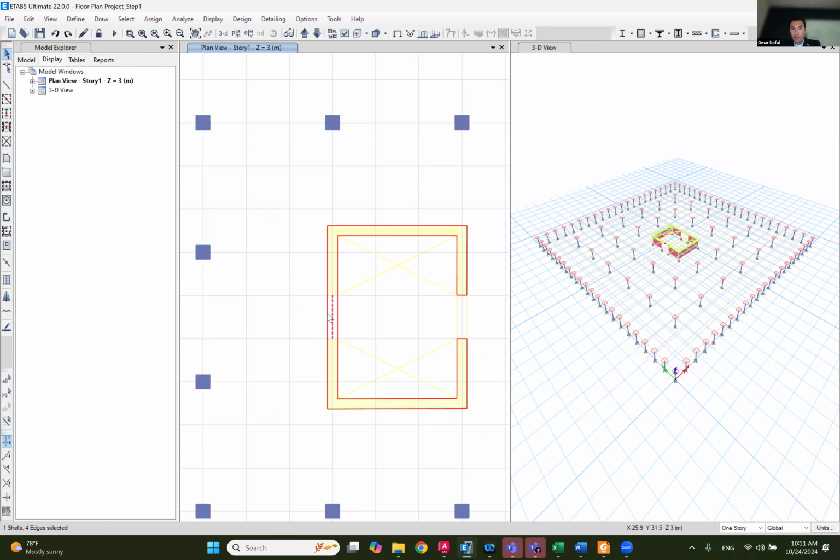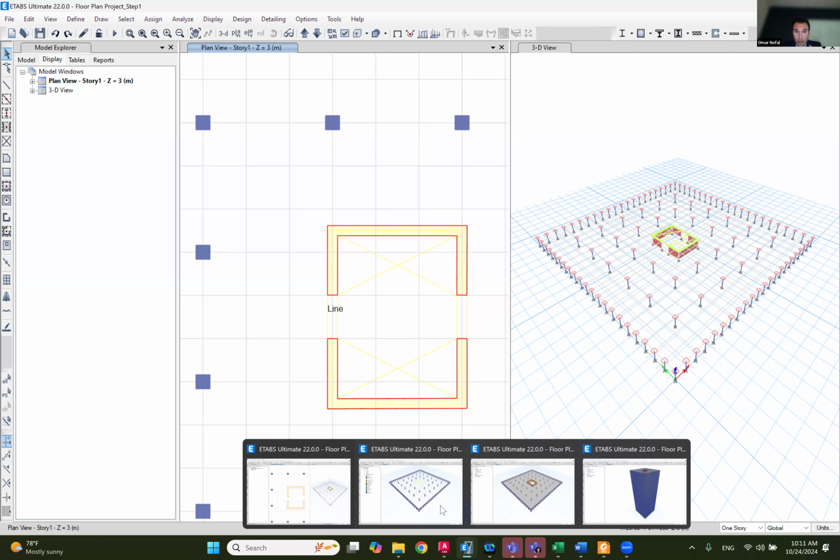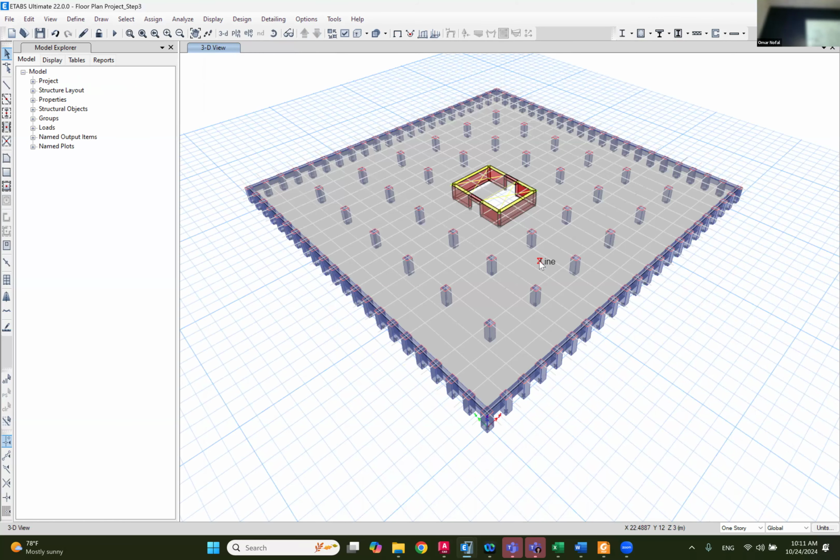All right. So for the sake of time, because it's really slow here, let's say that I already drew the spandrel beam here and here with the same dimensions that's in your base model. So you're gonna make the base model dimension, and you're gonna draw this. You make sure that the units here are meter and ton, whatever the units that you are comfortable with.